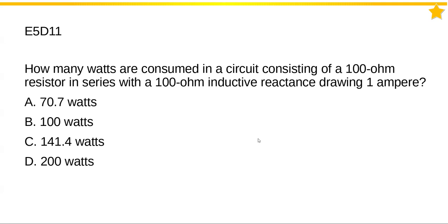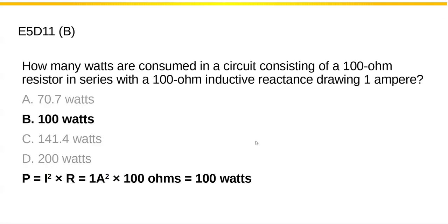Everybody ready? 100 watts. That was a trick question. You didn't need to calculate anything, because it said how many watts, not volt amps or volt amps reactive. So the only watts consumed were in the resistor.